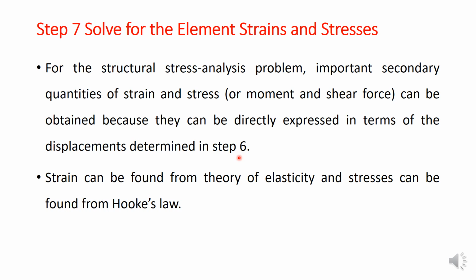In step 3 of FEM, I said that we can establish a relationship between displacement and strain. For example, in the one dimensional case, we can say that epsilon x equals du by dx, where u is the displacement in the x direction. So from there, we can find the strain in the x direction.